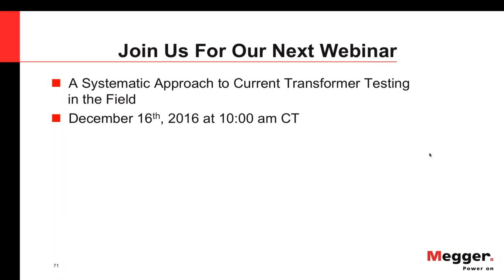All right, let me see. Another one. If we are fed from a utility on primary 12 kV service, what kind of CTs and PTs are required to monitor harmonics? Okay. Well, here's the problem, because you're going to be taking the measurements off a secondary of your PT and CT. So the secondary will typically be a low current. So you might use a 5 amp CT on there because the current can be that low on the secondary.